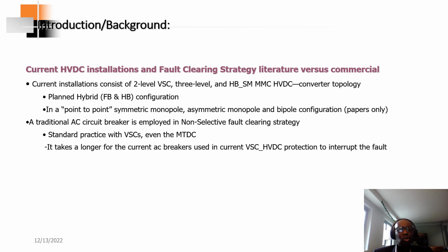And also you want to minimize the footprint. Also, the 2-level voltage source converters, the 3-level voltage source converters and the half-bridge sub-module modular multi-level converters lack the fault blocking capability and fault control capability compared to the full-bridge sub-module MMC.